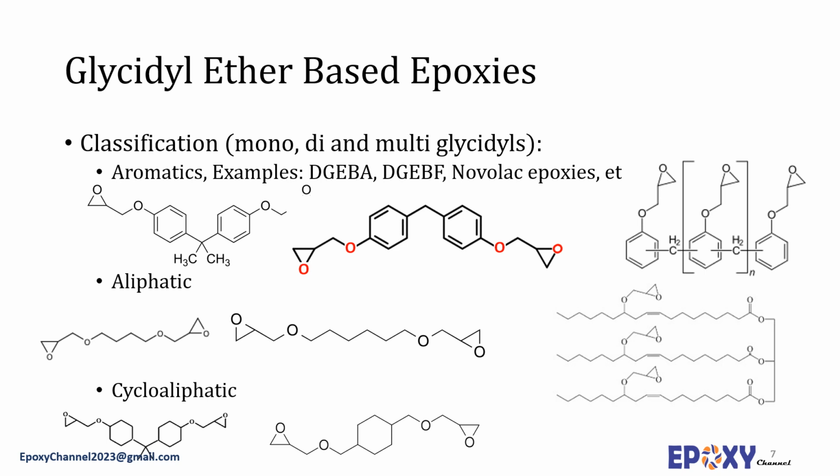The use of the diluent does affect the mechanical properties and microstructure of epoxy resins, whereas it reduces the viscosity and increases the processability. Another example is 1,6-hexanediol diglycidyl ether. Similar to the former one, its main use is for the reduction of viscosity in epoxy resin systems. It is thus an epoxy reactive diluent. The chain length helps give more flexibility to the epoxy.